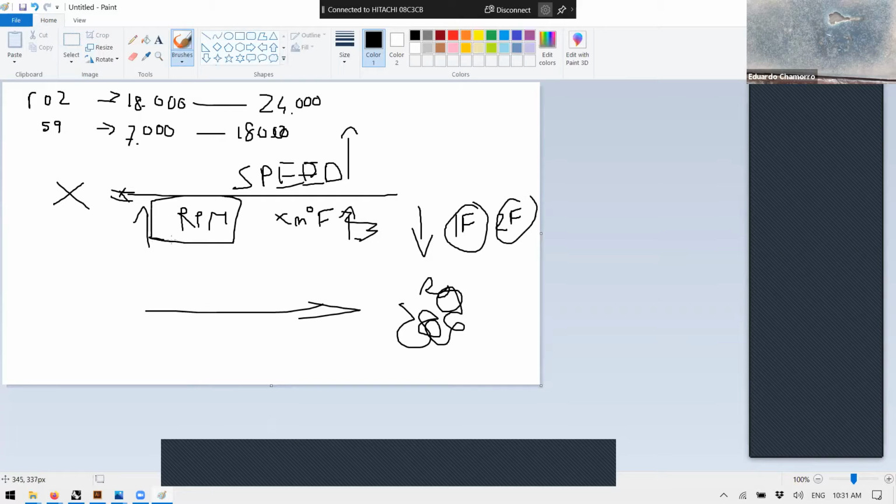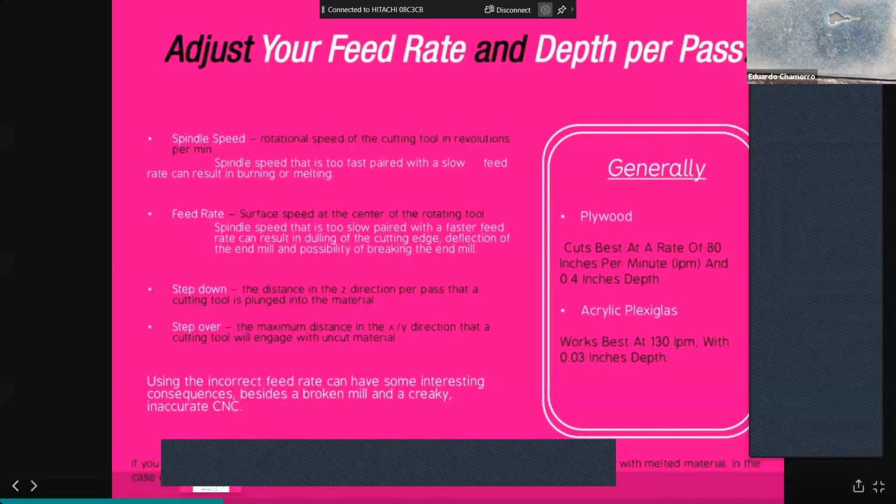What is the lower limit, the limit rate you can use? If you are not confident or you don't know exactly what you're doing, always go to the lower one, let's say the lower one in this machine. If I go to any machine, I will start with a mid-range that is 14,000 to 18,000. That's a really average range of kind of any standard CNC. But I have found CNC machines that range up to 40,000 RPM. Those are really fast. And what usually happens is that it's with router motors. Router motors, yesterday I explained, I don't know if you remember, that we have two types.